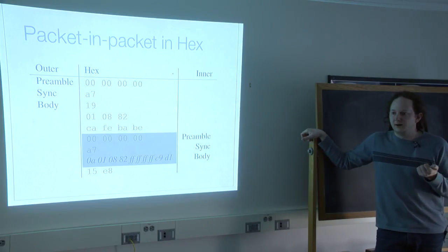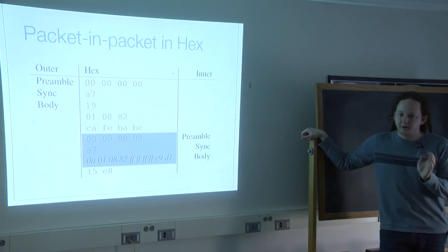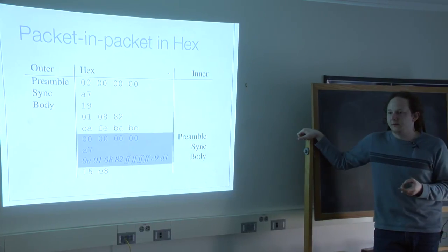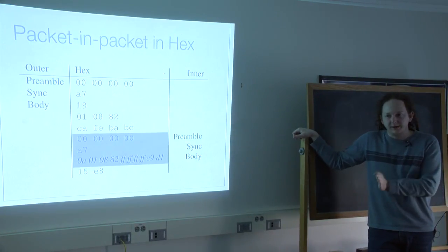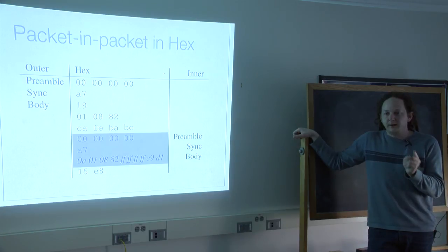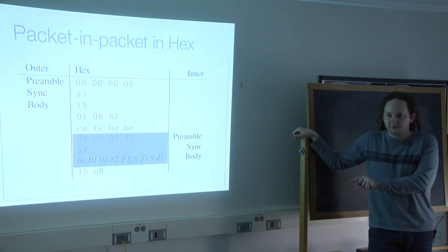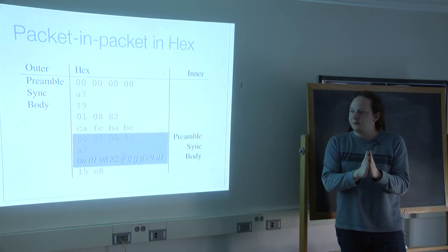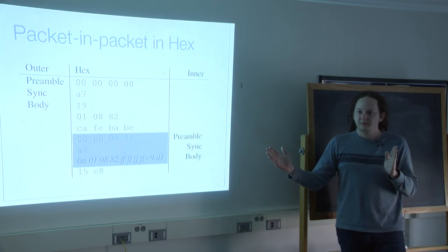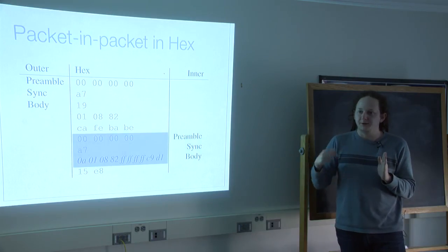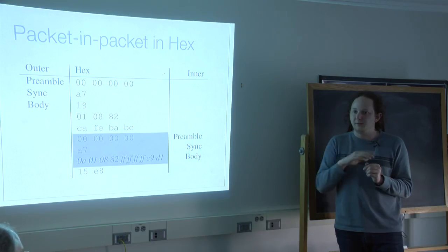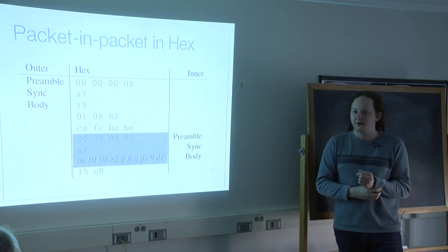Wi-Fi has a method of getting through interference, which is that it politely requests use of the channel, and then it uses it. Bluetooth has a method for dealing with interference, which is that it channel hops so quickly that any interference will only hit it on one of its channels. But this means that Wi-Fi is taking use of a channel for a long time, blotting out all of the Bluetooth traffic that tries to go across in that channel. And Bluetooth is hopping over every channel, transmitting garbage and interfering with the middle of Wi-Fi packets, and they collide